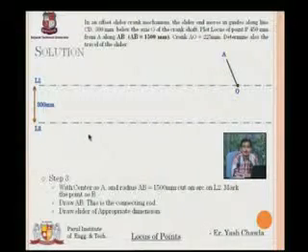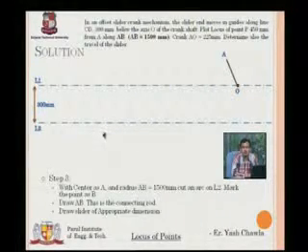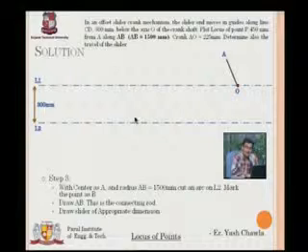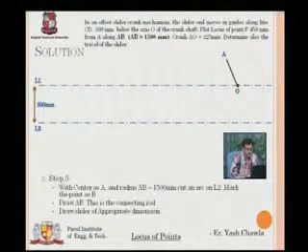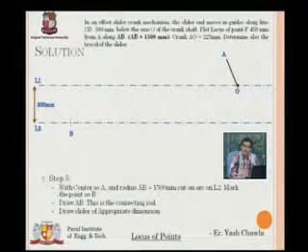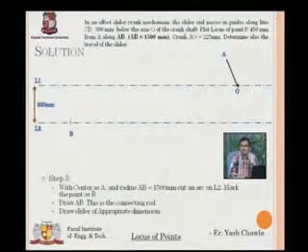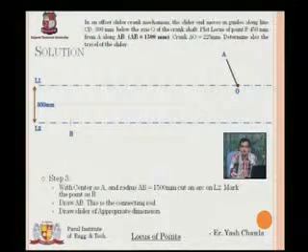So I will have the different positions of the slider on L2. With radius equal to the connecting rod and my center as A, I will cut an arc B on line L2. This is the initial position of the slider.